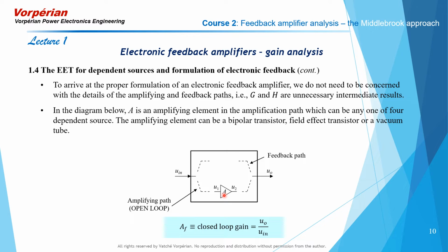Yeah, you can want it, but you know you can't get it. But wouldn't you want it to be large? In fact, if you don't have any large gain here, A, you have no feedback circuit. You just have a circuit. But for this to be a feedback electronic circuit, A has to be large, and ideally it's got to be infinite.